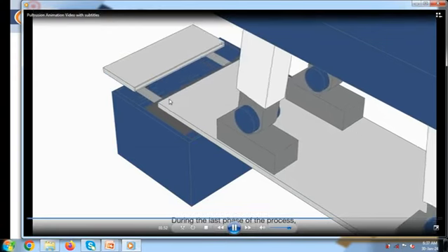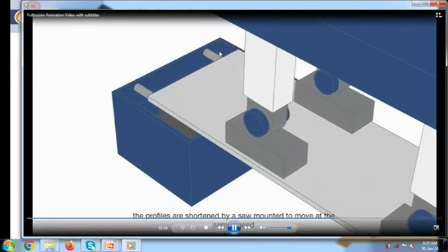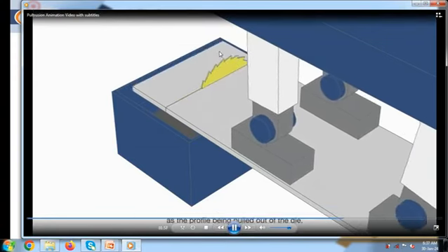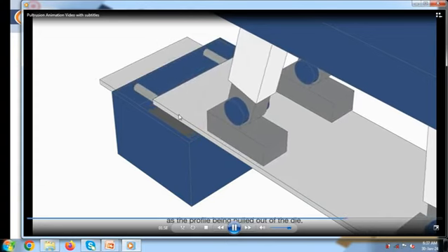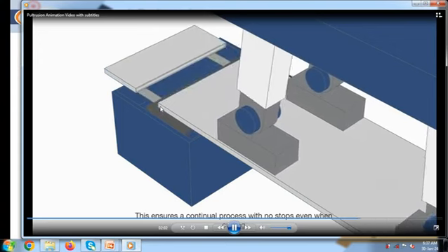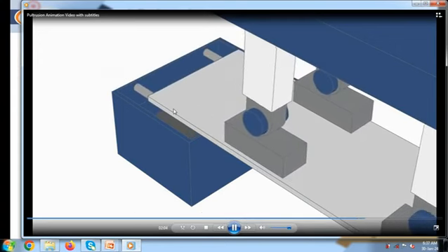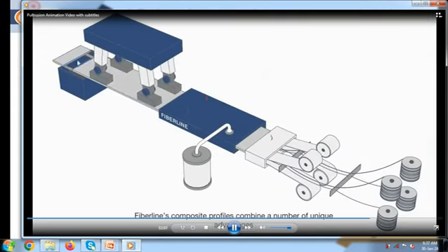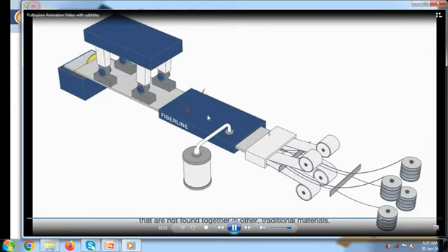Now here you can see that your laminate sheet gets separated. Into the required shape as well as the required size, we have to provide the guider, and this will be a cut saw. With the help of this cut saw, we can cut this portion of the laminate. So this is just an animation of the pultrusion process.